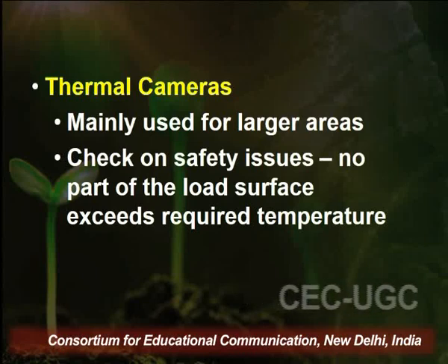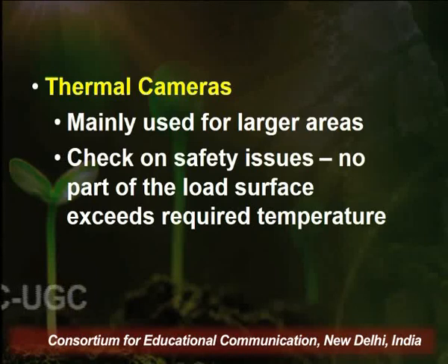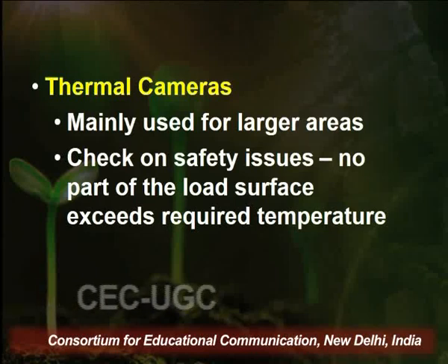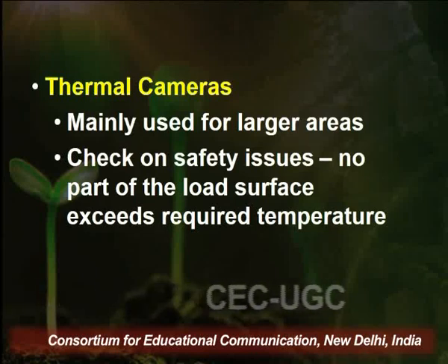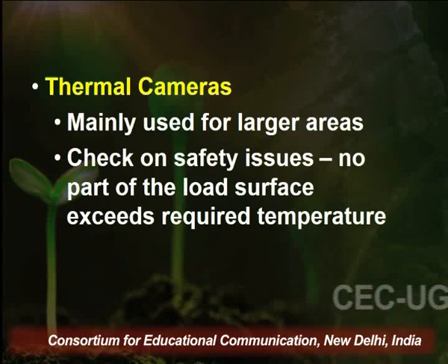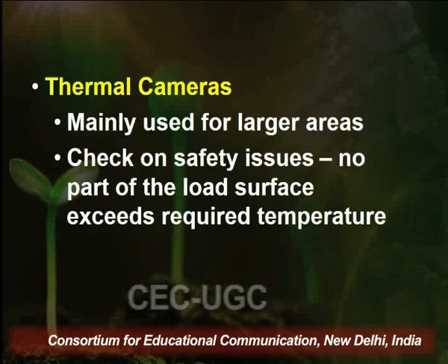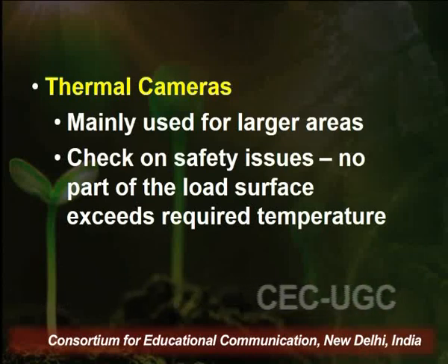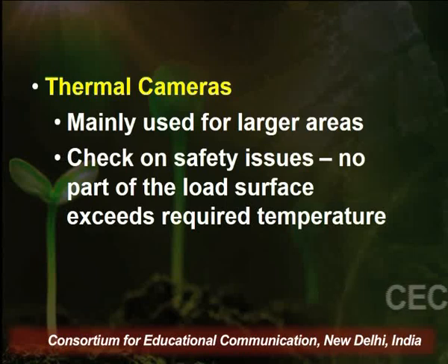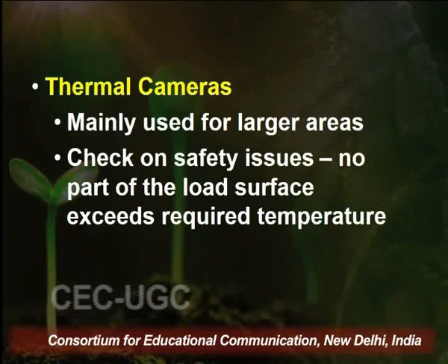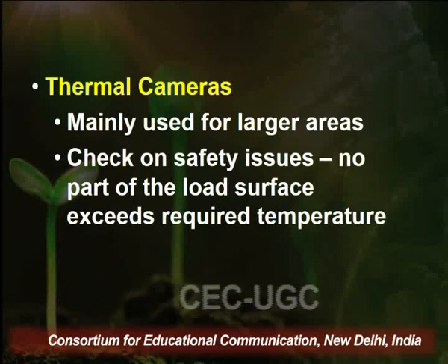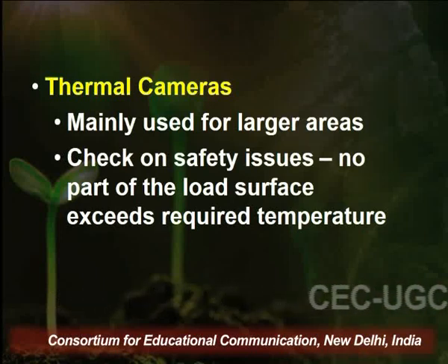reactors. Again, mind you, these thermal cameras are a non-contact method, and therefore they will provide you only the surface increase in temperature, and therefore again their utility is quite limited in case of microwave extractors, or it is only limited to the industrial use, with these demerits, because they only measure the surface temperature and they just tell you whether the temperature has exceeded beyond the prescribed limit.